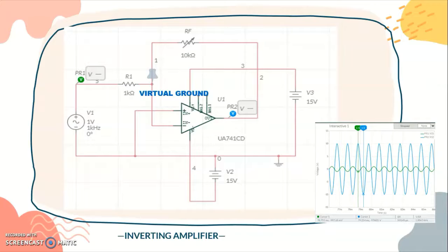What is virtual ground? The concept of virtual ground is only meaningful for operational amplifier circuits of closed-loop configuration. After all, operational amplifiers are differential amplifiers with infinite gain. Hence, virtual ground is for the case when the feedback circuit acts to control the voltage difference between the two terminals small enough to make the output linear and below VCC.